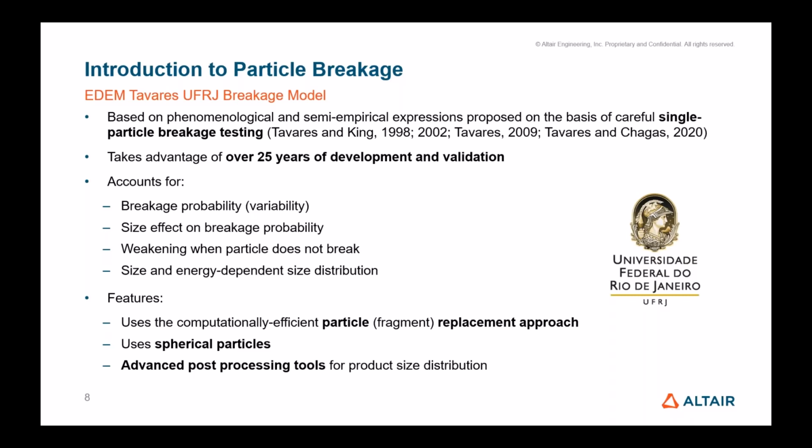Some key features of this model are that we are using a very efficient particle replacement approach, which I will touch on in a slide later on. We're using spherical particles, which is basically the methodology that the model has been validated for, and I'll touch on this more later when I talk about the fragment replacements and energy calculations. And also in EDEM, we have very advanced post-processing tools specifically dedicated for that model that will allow you to see great detail of the data produced when a simulation is run with the EDEM breakage model.